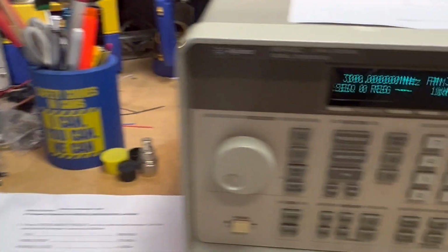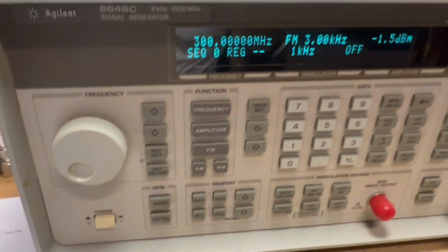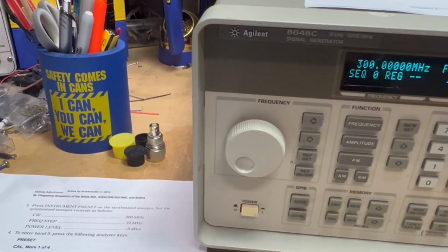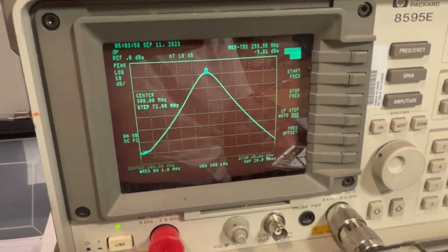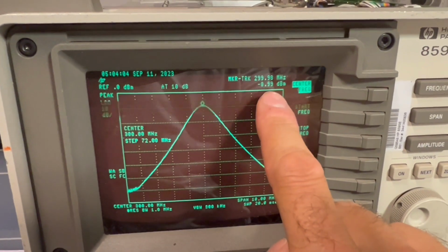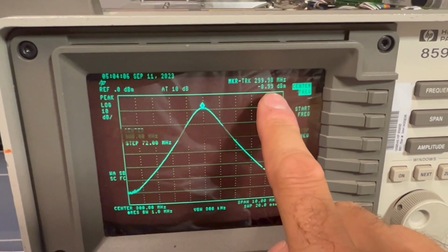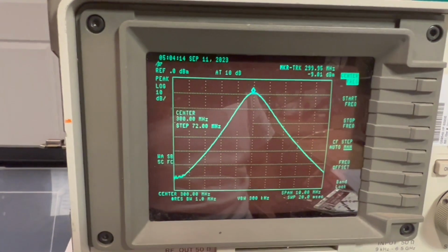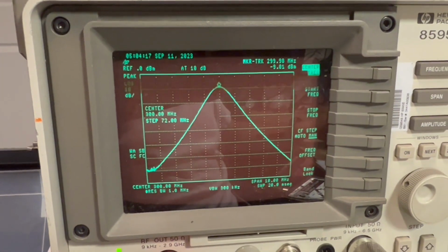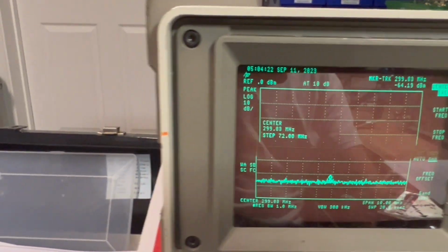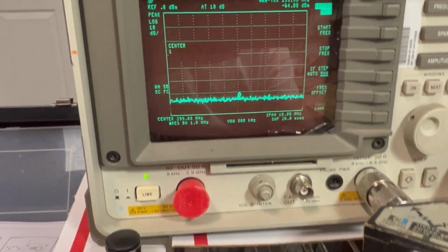And what we'll see now is as we change the frequency here, and we adjust the frequency, the power level going into our spectrum analyzer for a -9 dBm marker track reading here, then we can take the relative signal on the power meter up there. So we're looking at 0 right now, so I'll go ahead and take the first reading. So I'm going to put the signal generator down to 12 megahertz, and we'll put the spectrum analyzer at 12 megahertz.